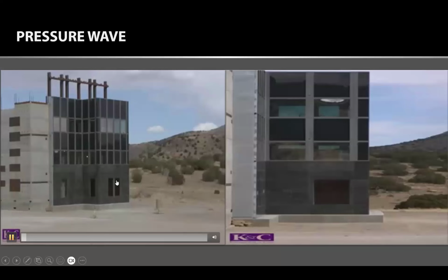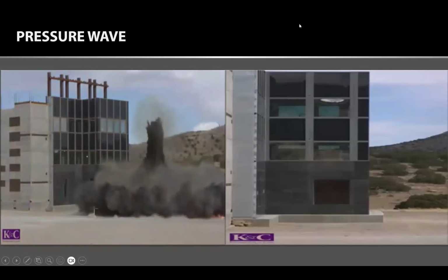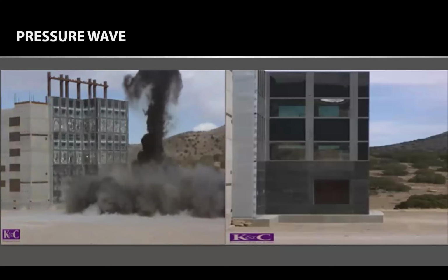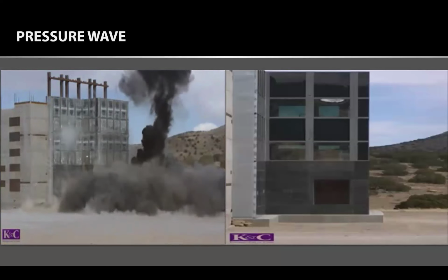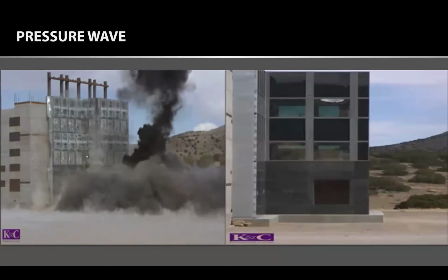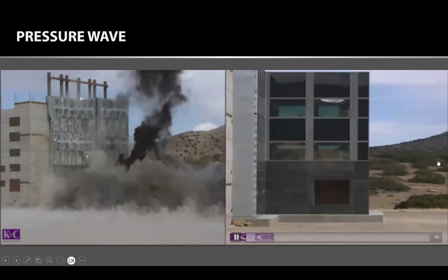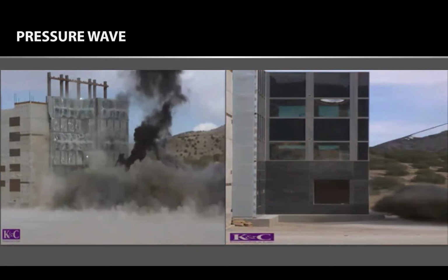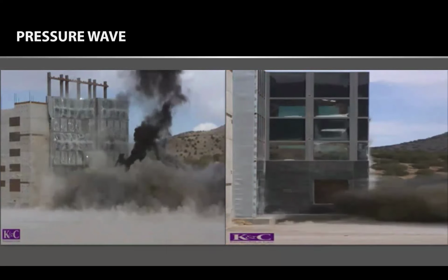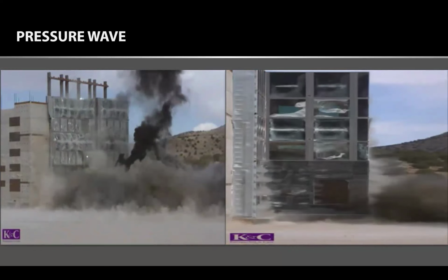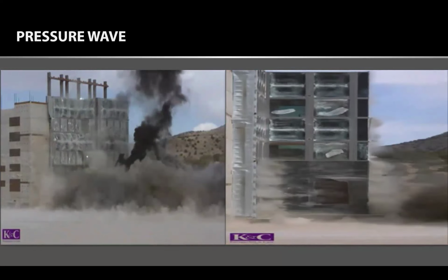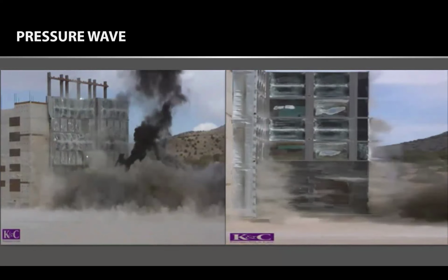The second video that you will also see will be what we call the positive pressure or the negative pressure. And negative pressure can be just as detrimental to a building because it can actually suck the doors and the windows right off the actual building. And at that point, people have gained access to the insides of these buildings. So the first shock wave that you will see here, there's the positive pressure hitting the building. And watch here, you'll see it go in reverse. It almost looks like the building's going to rewind. And there's the negative pressure that is essentially exerting a force onto the surface of that building as well.